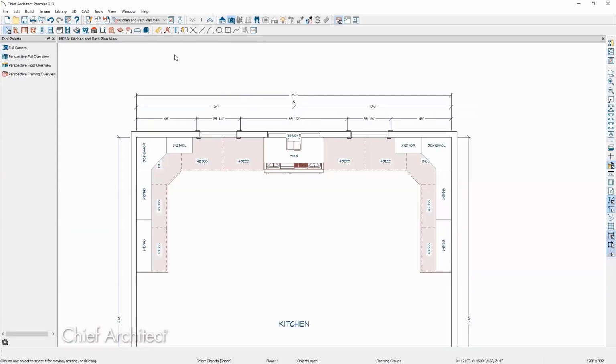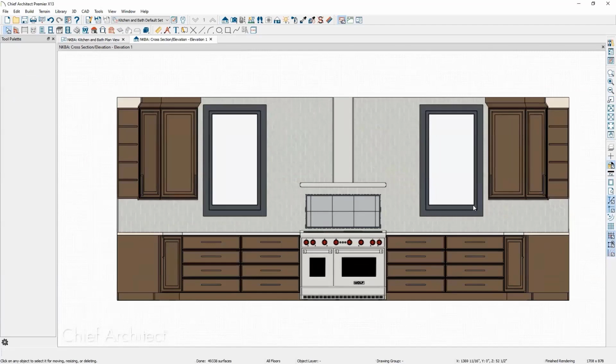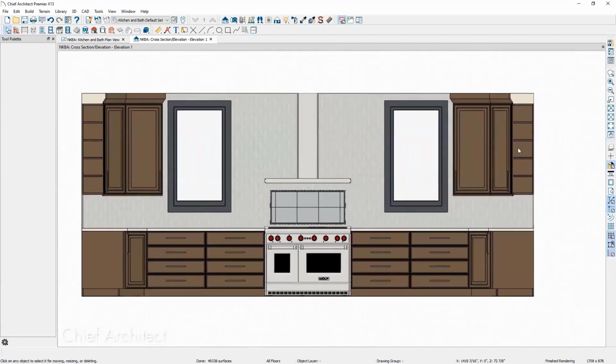And then I am going to go up to our elevation tools and select the wall elevation. And right here is where I'm going to click and point it along this back wall. And you can see that quickly creates a clean looking elevation. And if you wanted to modify this so that it had a mask over these drawers for that wall cabinet, you can do so just using the CAD tools up here. You can also use your text tools if you wanted to add text.